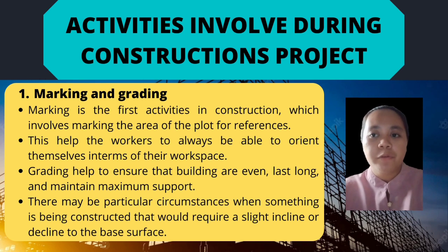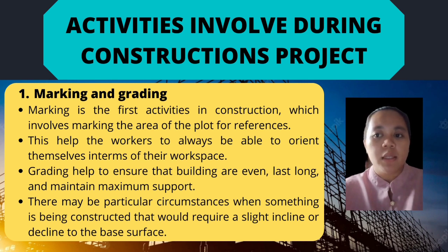Next, we move to activities involved during a construction project. Number 1 is marking and grading. Marking is the first activity in construction, which involves marking the area of the plot for reference. This helps the workers to always orient themselves in terms of their workspace.